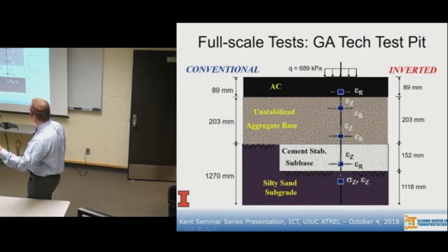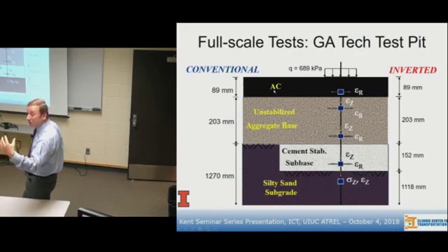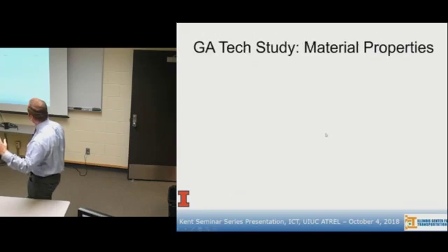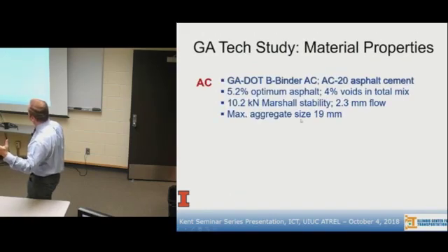So these are all the different locations that I was doing my modeling with anisotropic base, nonlinear, stress-dependent, all of those things that GT-PAVE could do. That was my PhD work, right? And I was able to come up with responses predicted at various locations in the pavement.